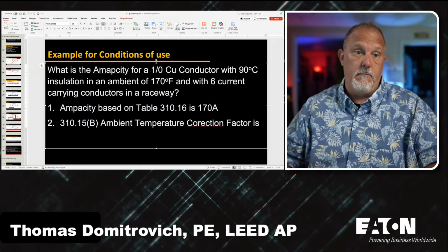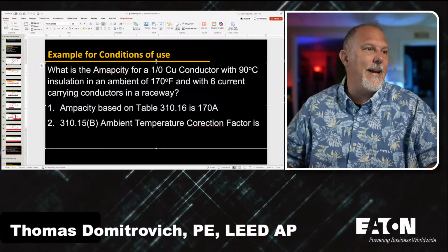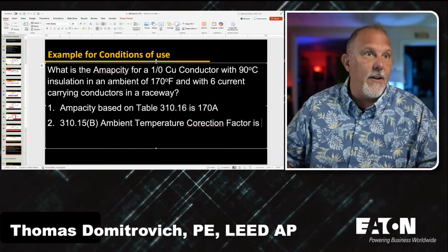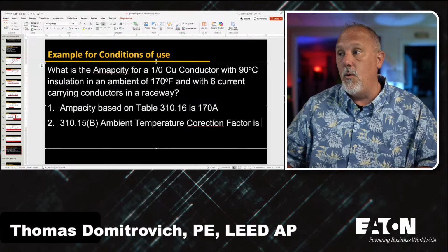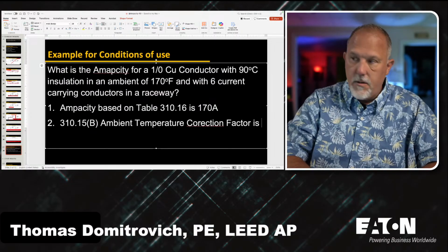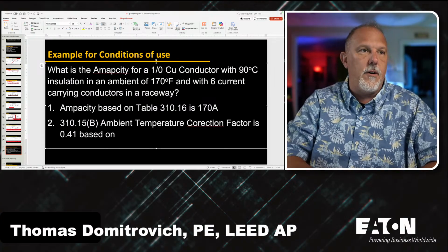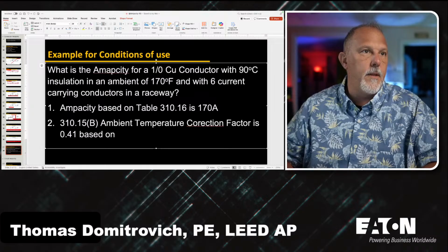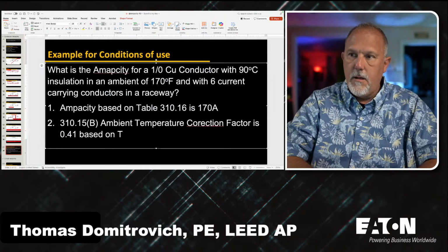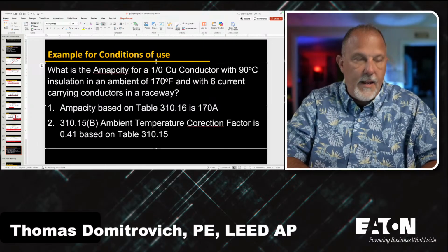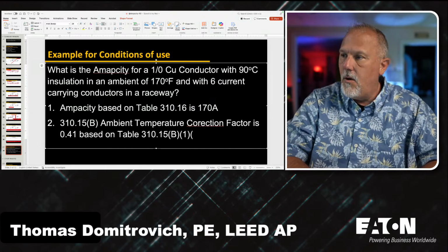Whoa, that's hot. Oh shoot, there it is, 107. I had to pick one that wasn't on the table. So 90 is 0.41. 0.41 based on Table 310.15(B)(1).